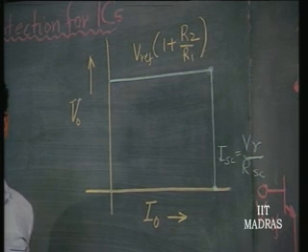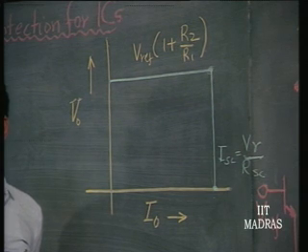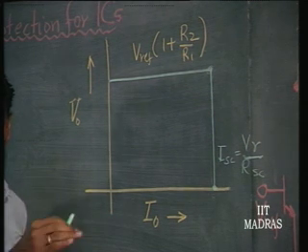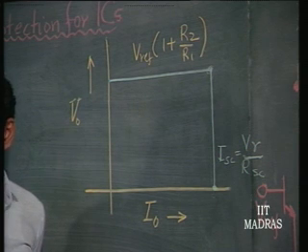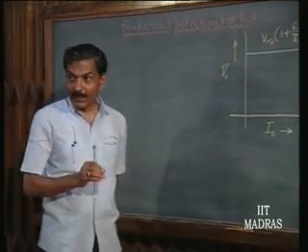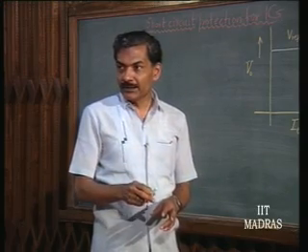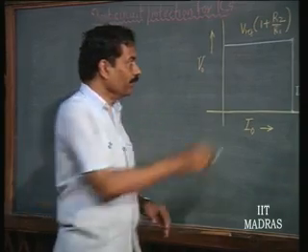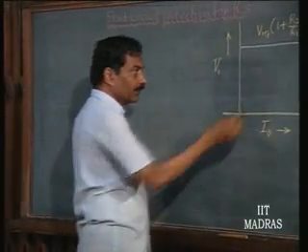the IC. Therefore, we would like to immediately sense the load and find out that the load is in excess of what is correct, and thereafter we want our own dissipation in the IC to be as low as possible until somebody comes and rectifies the error. So, we have to sense both current as well as voltage for that purpose, because we should know what is the voltage and what current I should sustain in order to sustain that voltage, which can be anywhere between this and this.